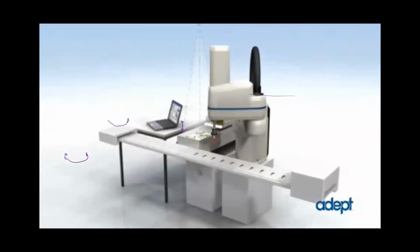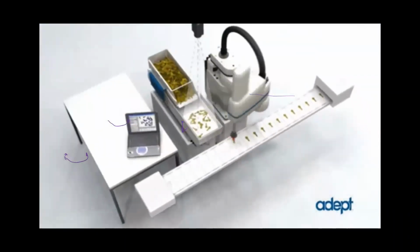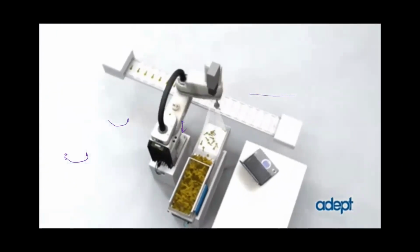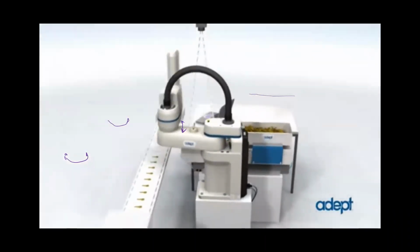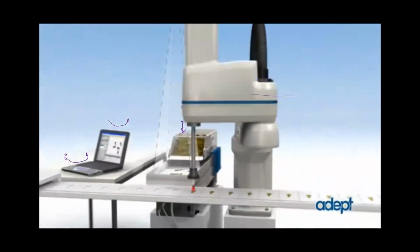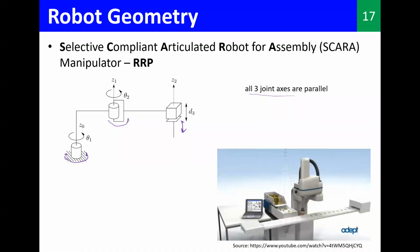So now you have to think from the other way around. Let's say you have to build something, let's say, I don't know, like a robot that can do soldering on something which is there on a tabletop, right? So you have to think whether this particular robot is suitable for that. Now you can see why this SCARA robot, the question I actually asked before, is not suitable for something like spray painting of a vehicle. So this is very good and suitable for tabletop kind of applications, right? All right.